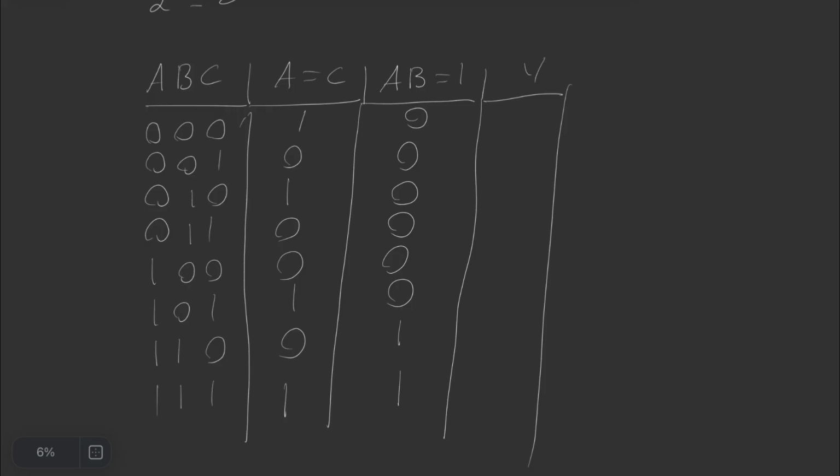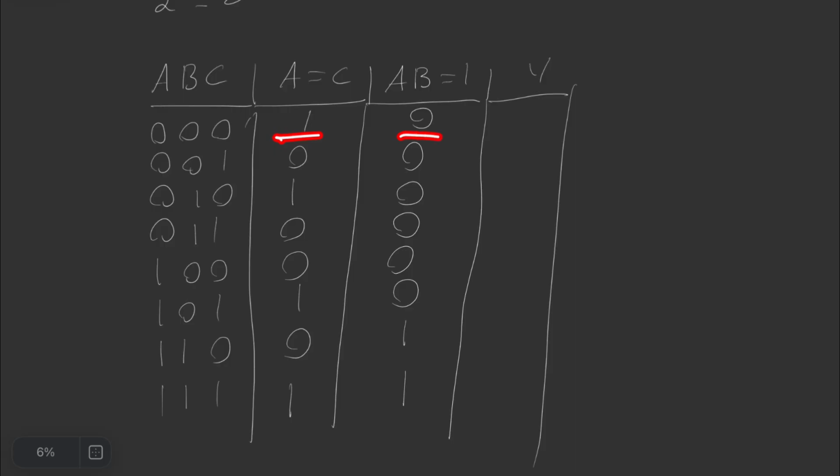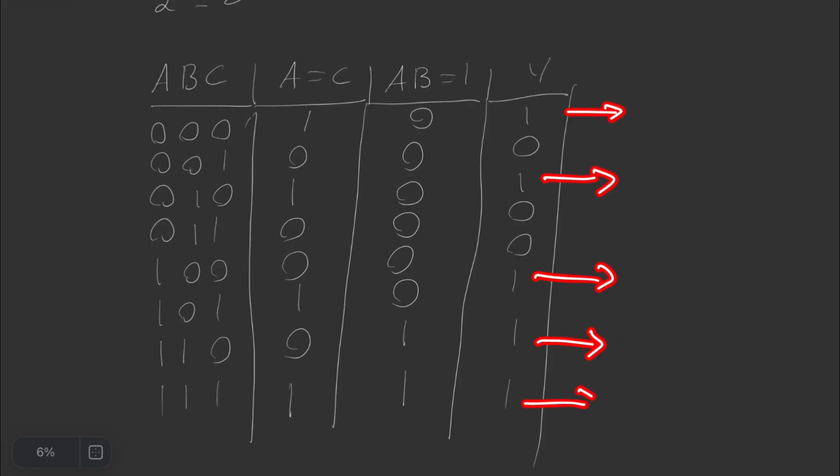Okay, now if any of these conditions are met, our value will be 1, and that is the same as ORing the values. So, condition met, not met, met, not met, not met, met, and met. So right here, this is the truth table of our output. This is the truth table of our whole circuit. If you used sum of products, you could get the Boolean expression and draw the circuit that applies these conditions. You could also use K-map simplification, but that is for another video.